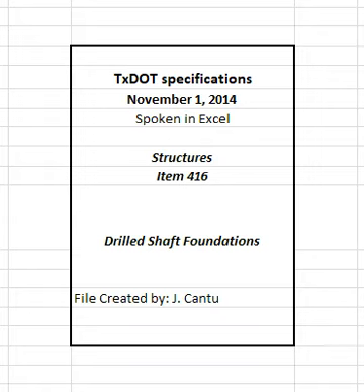a single unit. Extend the reinforcing steel cage as follows if the shaft is lengthened beyond plan length unless directed otherwise. Extend the cage to the bottom for shafts supporting structures other than bridges. Extend the cage to 25 feet or to the bottom, whichever is shorter, for bridge shafts with plan lengths less than 25 feet. Do not extend the cage for bridge shafts with plan lengths at least 25 feet that are lengthened less than 33% of plan length.